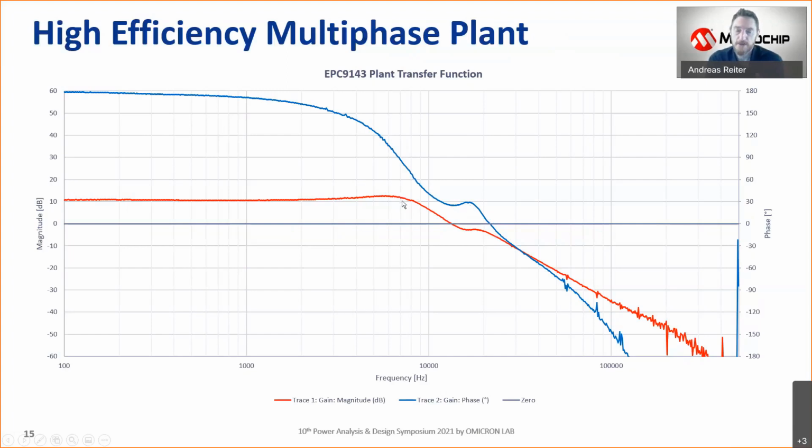So this ping pong between both converters may result in charges which are flowing between both phases. And that then manifests itself as yet another pole that shows up at twice the resonant frequency. And this pole is visible in pretty much every control mode. The only way to properly eliminate this would be either hysteretic mode, or a peak current mode.